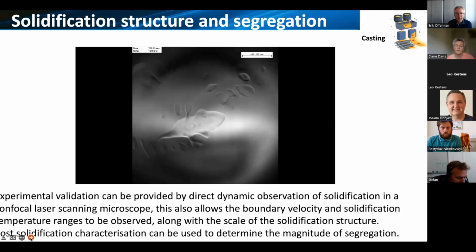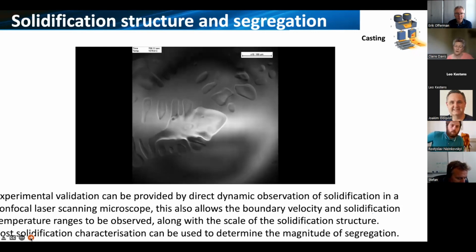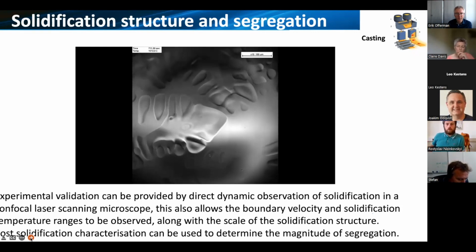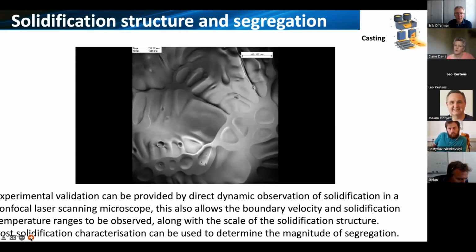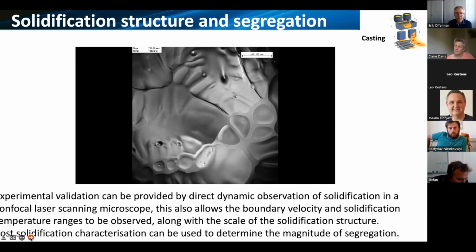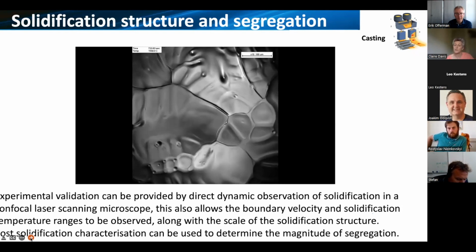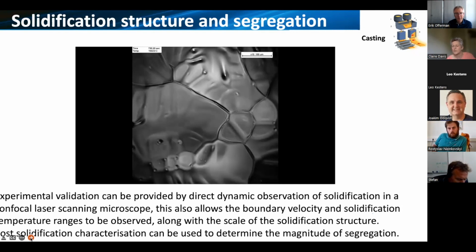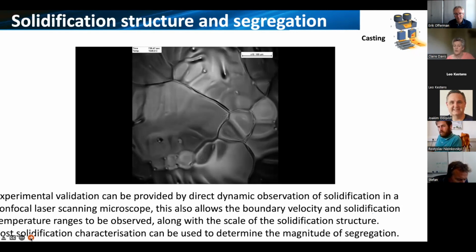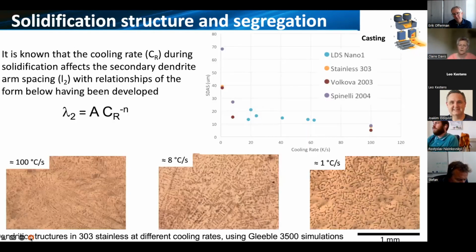And the thing you might have noticed just at the end of the video, before it looped back, is at the end of solidification, we get then the transformation to the austenite, and actually you can see the austenite grain boundaries. And should we continue with this, you can see the austenite grain growth, and that's the thermal etching effect. So just here, we can see some of those boundaries. All of this is really important to build up some of the relationships.